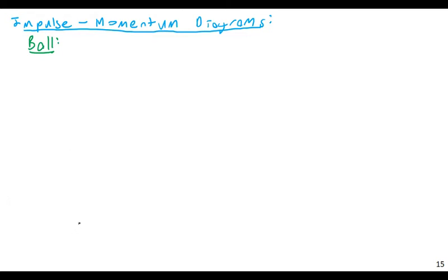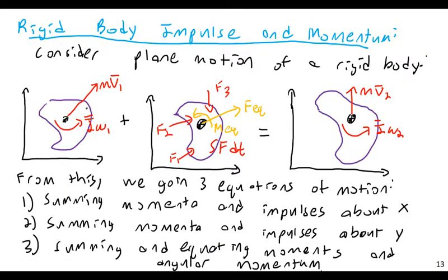And we'll look at this here. So all of this is going to be based off of this idea here. Whenever I draw an impulse momentum diagram, I'm going to have an initial state of momentum, both linear and angular if applicable, the final state, both the linear and rotational as appropriate, and then I'm going to have the impulse. So we'll have an initial momentum diagram, a final momentum diagram, and then an impulse diagram. And that's the basic method for setting these things up.